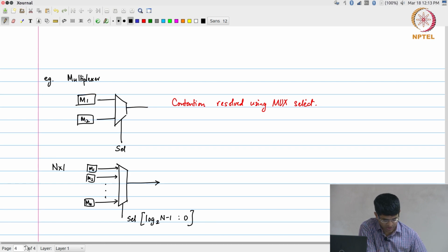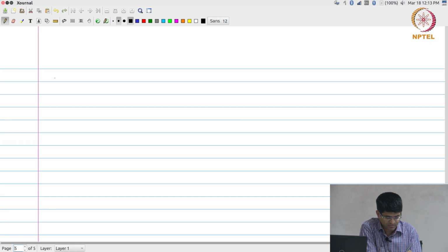Another approach that can be used is using so called tri-state logic, right. So, tri-state essentially deals with the fact that the transistors that are used in order to actually implement these logic gates, under certain conditions can be made to behave like a high impedance terminal, right, meaning that for all practical purposes it is just disconnected from the rest of the circuit.